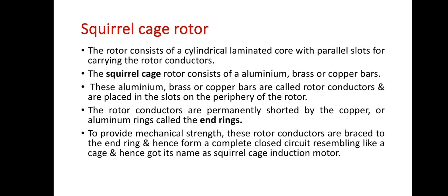The rotor conductors are permanently shorted by copper or aluminum rings. It is called end rings. So to provide mechanical strength, these rotor conductors are braced to the end rings, and hence form a complete closed circuit resembling a cage, and hence it is named as squirrel cage rotor.